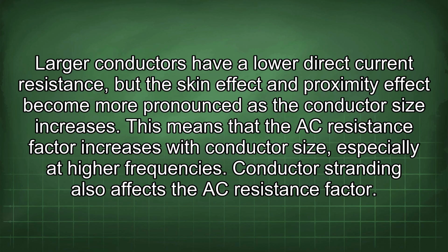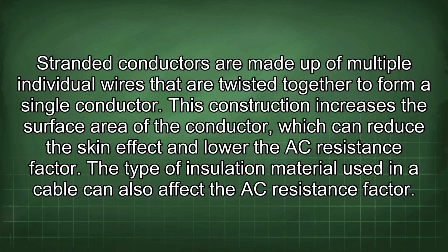Conductor stranding also affects the AC resistance factor. Stranded conductors are made up of multiple individual wires that are twisted together to form a single conductor. This construction increases the surface area of the conductor, which can reduce the skin effect and lower the AC resistance factor.